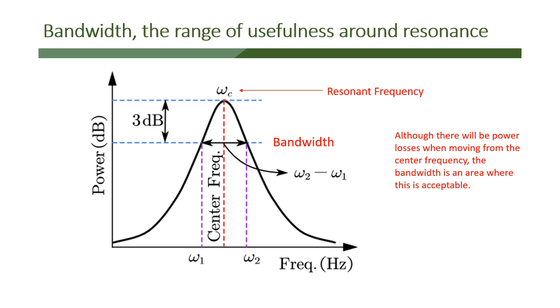You may not always be able to touch the antenna and feel it getting hot, but it is heating up when it's off frequency, because it's not radiating all the energy. It's going to go somewhere. It's going to go out as heat, even though that heat may be so small it's almost imperceptible at times. And if you have enough power, it might be perceptible, so be careful.